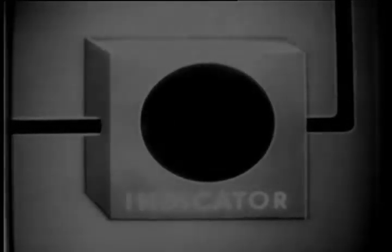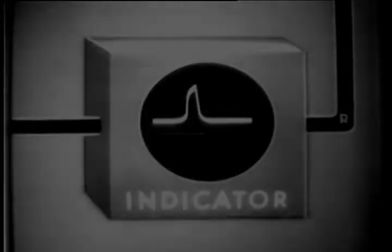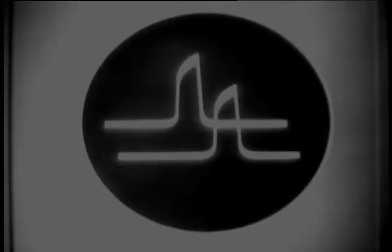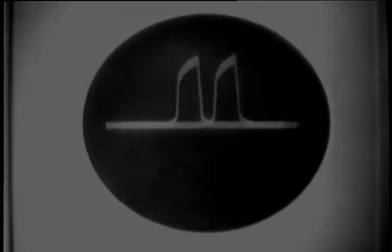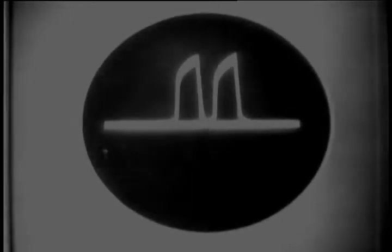So that now you have the set sending out a pulse through one lobe, waiting for an echo, then switching to the other side, sending out another pulse, and again waiting for an echo to return before switching back again. Furthermore, the echo from each lobe appears on its own baseline. Normally, the two baselines are superimposed and appear like this. But there are still two separate baselines and two pips. On the actual scope, you may see them like this, and by adjusting your spread control, you can govern the distance between them.